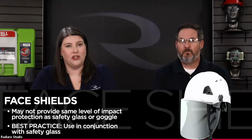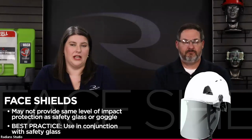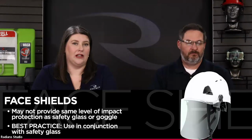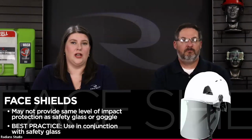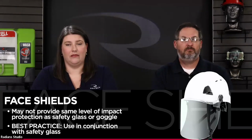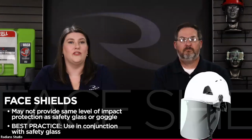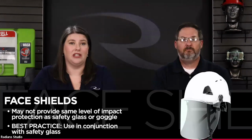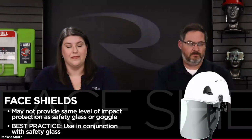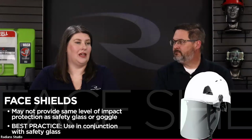A polycarbonate face shield, on the other hand, which is what we've got in our illustration here, would offer you impact protection. That's because it's made of the same material as the lens on your safety glass or your safety goggle. Those are going to ship in their rigid form. They're not flimsy. Torque them, they're going to break at some point. But if you do have to have that impact protection coverage across your face, you're going to need a polycarbonate face shield. Acetate is another material out there, and it actually offers the best chemical resistance.